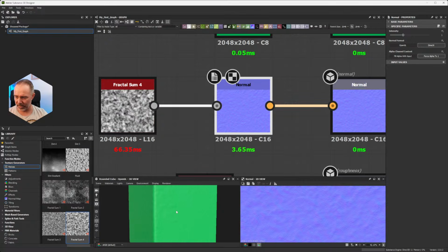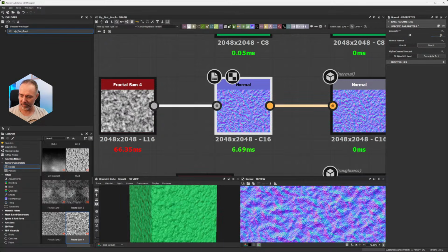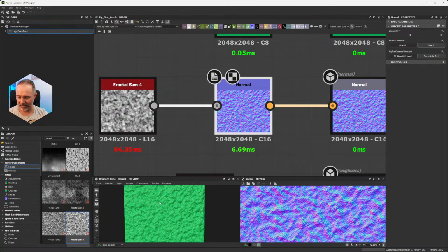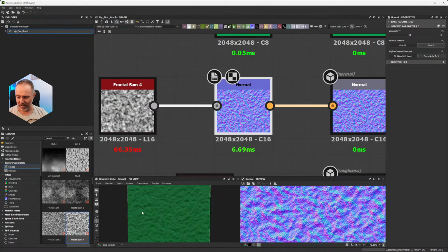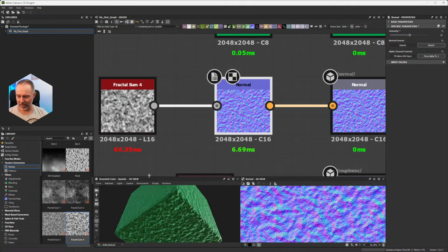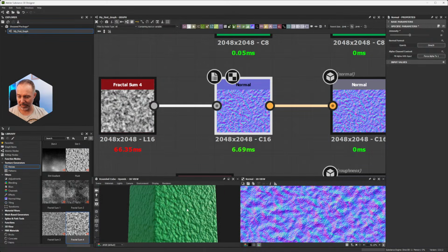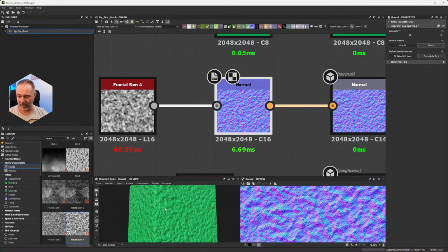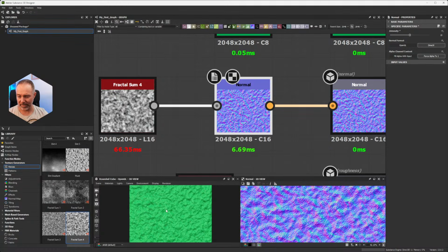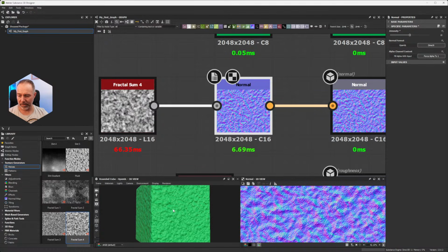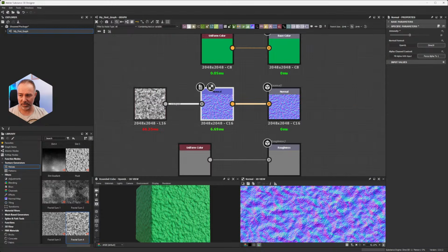And now if you look at the object, I'm going to push a bit to 10 because by default it's a bit weak. You see that it does as if there were some asperities. Meanwhile, it's completely flat. But it's a way to trick the engine and to give nice effects. By the way, to make the rotation of the light here, it's a Control-Shift right click. Once again, if you have any question at any point, just tell me.